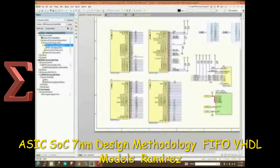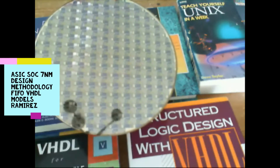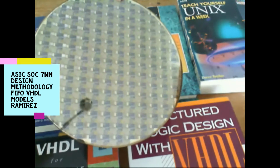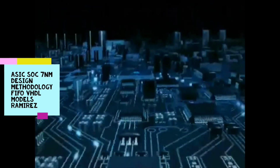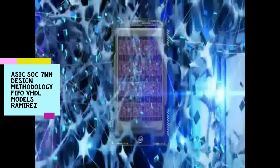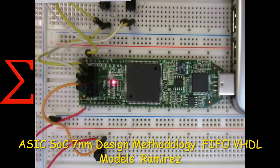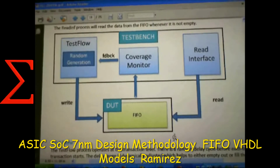The read_file command reads several different formats, that is .vhd, .v, .ddc, .db files. It also performs the same operations as analyze and elaborate in a single step. And it creates the .mr and .st intermediate files for VHDL. However, it does not execute the link command automatically.